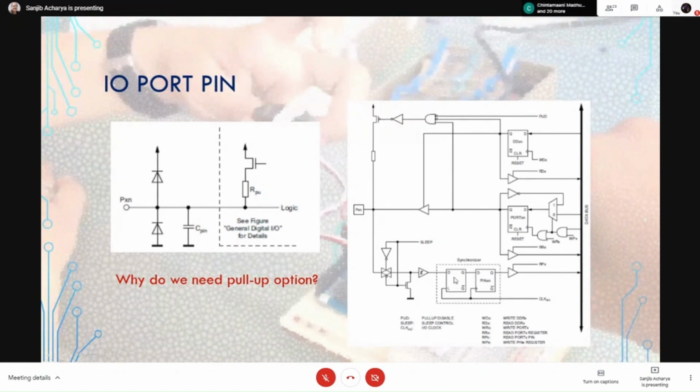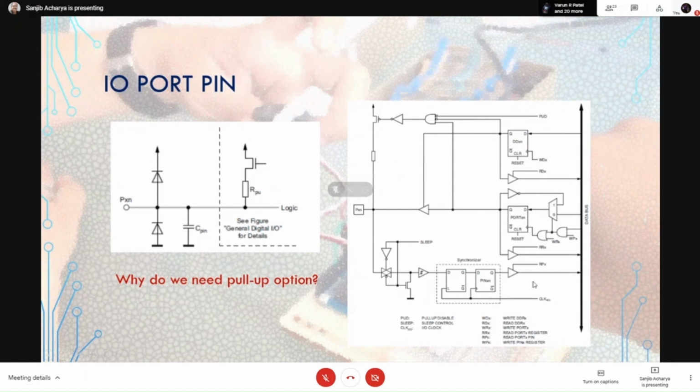And as you could see, there are two flip-flops kept one after another, in order to make it metastability hardened. So this is basically called a synchronizer. And then you have some buffer, and here also some gates to configure.